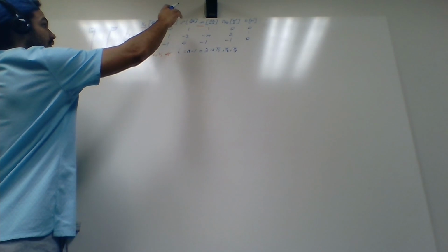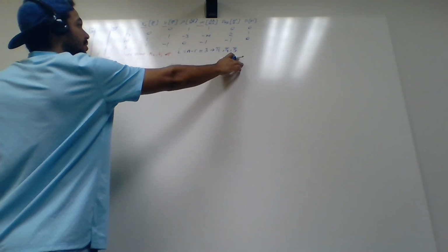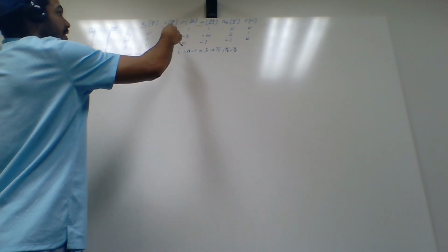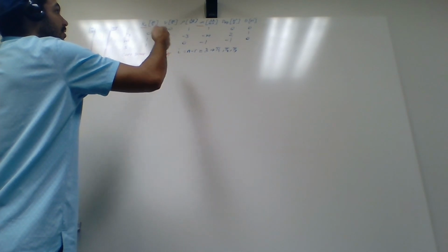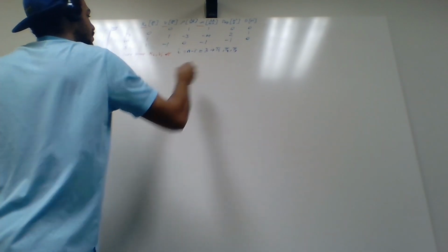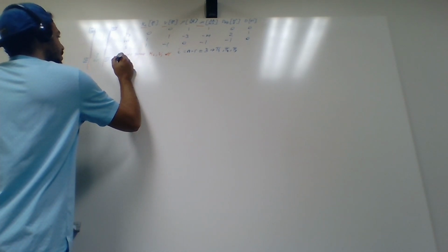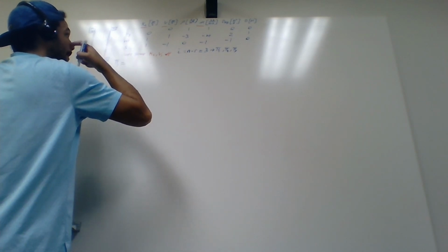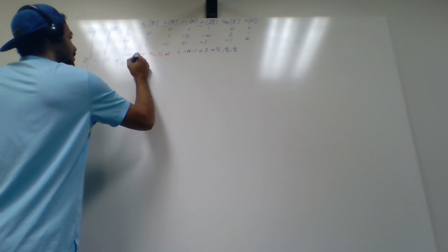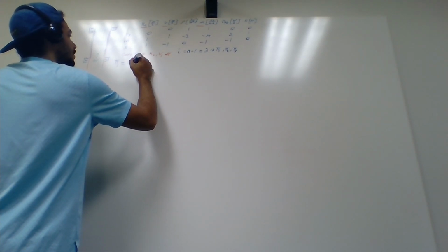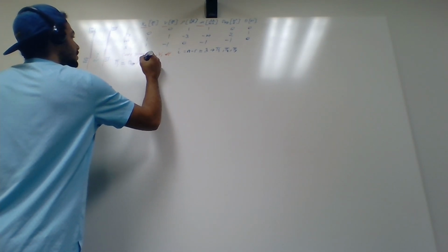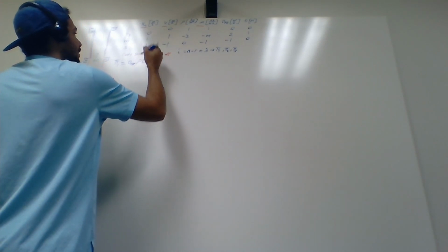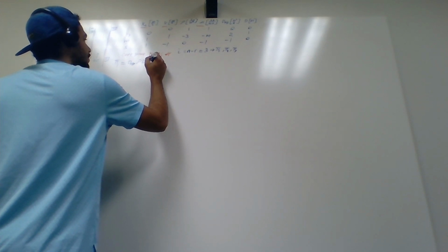So now we just plug in. Pi 1, 2, and 3 will each contain the non-core group values, then 1 of every core group value per formula. So we're going to say pi 1 is equal to the diffusivity times the density times the diameter. Then our core group value for pi 1 will be the mass transfer coefficient.